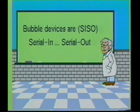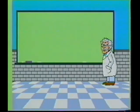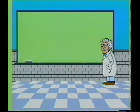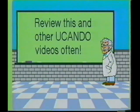The operation of the bubble memory is very similar to a shift register whose shifting frequency is determined by the frequency of the rotating magnetic field. Internally, the bubble device uses major and minor loop organizations. The major loop is used for read and write operations, and minor loops are used to store the data. This concludes this video on memory devices.